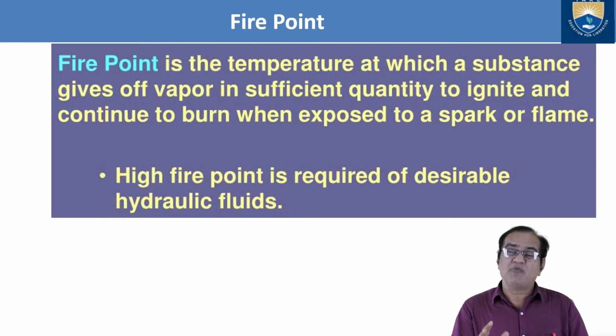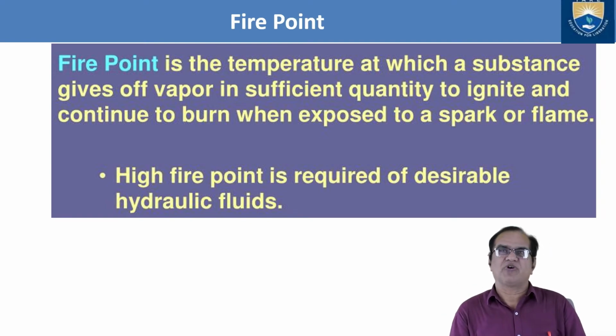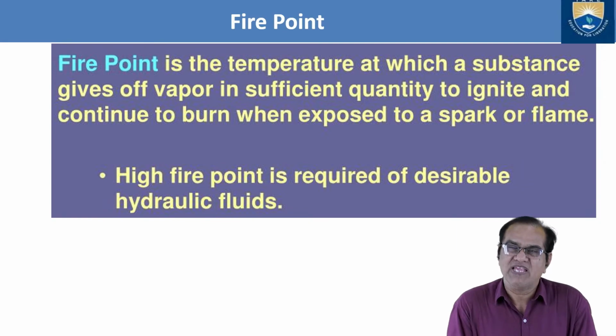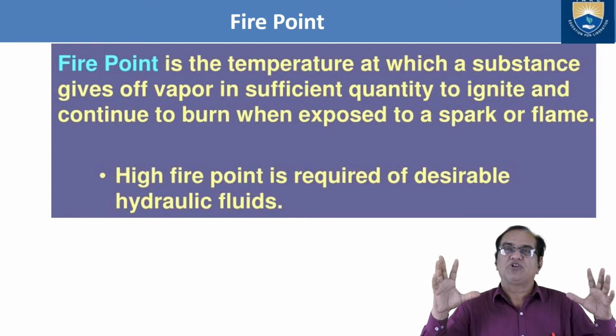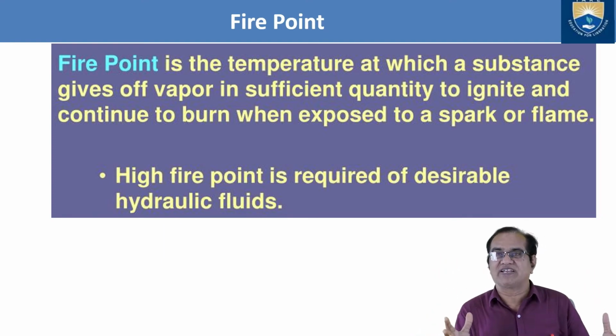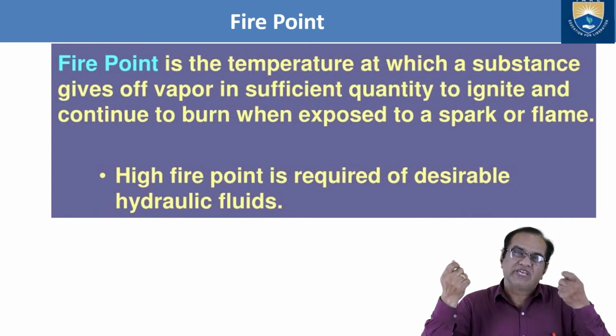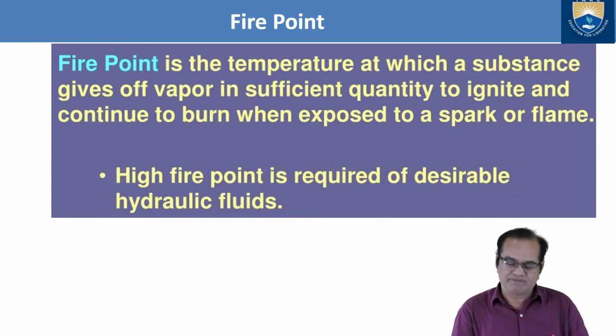So the fire point is higher than the flash point. A high fire point is desirable for hydraulic fluids. So if you want a good hydraulic fluid, a high fire point and high flash point should be there so that it can resist fire, because you know that at high altitude you don't have any firefighter. You cannot bring a truck to put out the fire on the system.